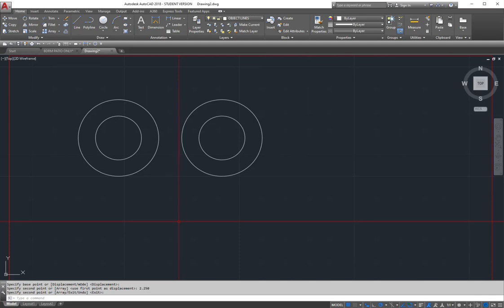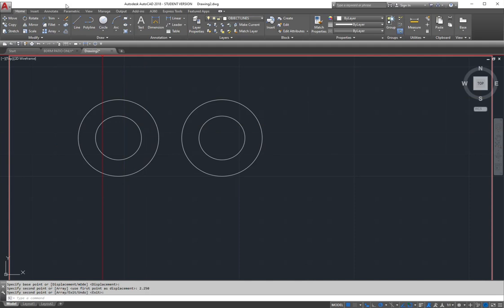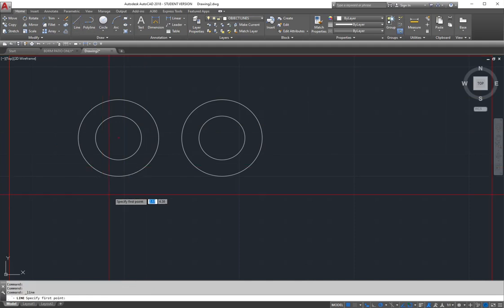As you will see on your exercise, there are a couple of lines that I need to create. So there will be a line that goes from the quadrant point to the quadrant point right here, and then I go line again from the quadrant point to the quadrant point. Remember, it's going to be important that you have your object snap active with the right locations, whether it's quadrant, center, tangent, and so forth, midpoint.